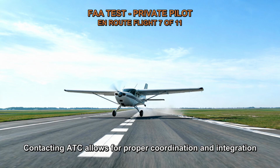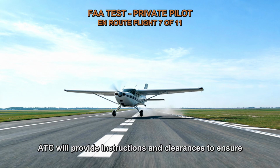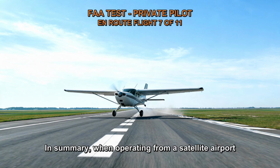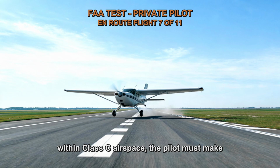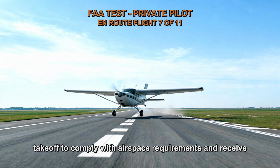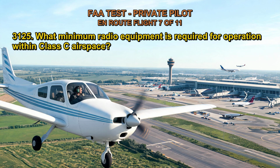Contacting ATC allows for proper coordination and integration of the aircraft into the Class C airspace. ATC will provide instructions and clearances to ensure safe operations within the airspace. In summary, when operating from a satellite airport within Class C airspace, the pilot must make contact with ATC as soon as practical after takeoff to comply with airspace requirements and receive appropriate instructions for operating within the airspace.